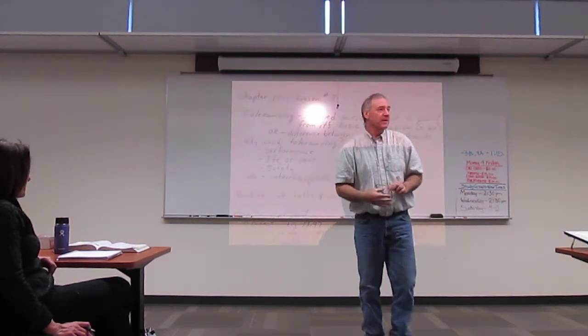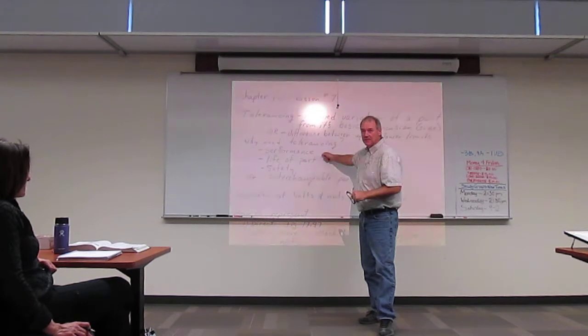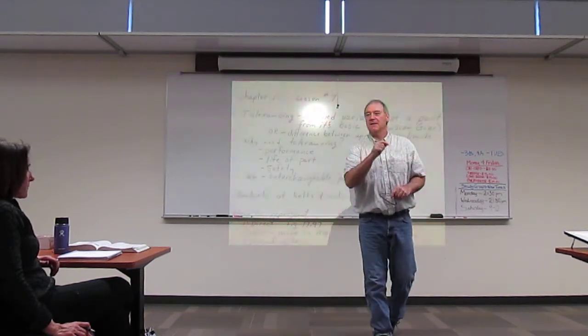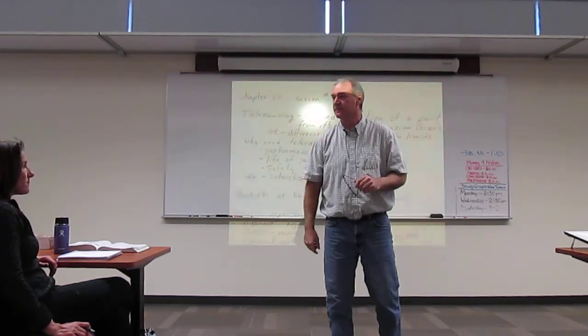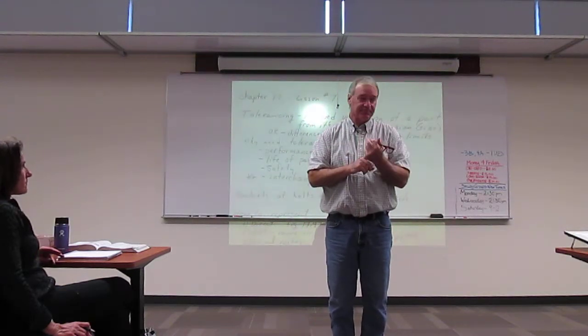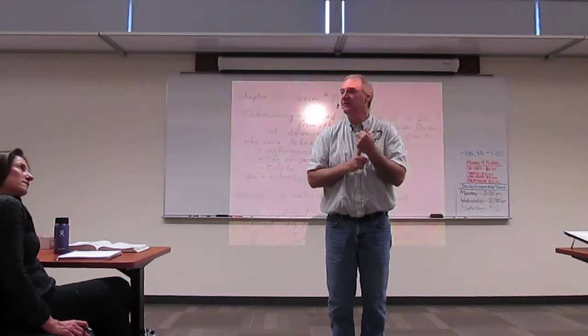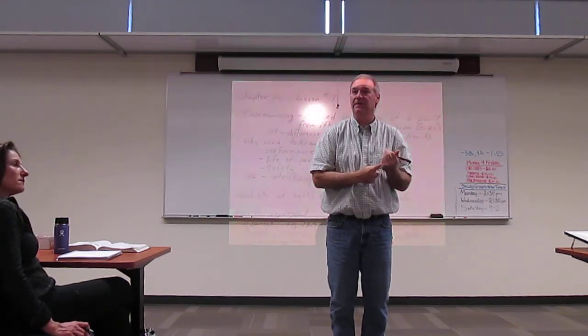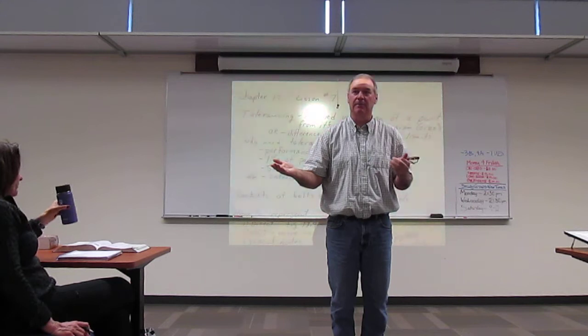Believe it or not, we do build a lot of parts with very sloppy tolerances specifically so that they will break. There are two reasons companies do that. Number one, they want the part to wear out because it's a cheap part and it's protecting an expensive part.